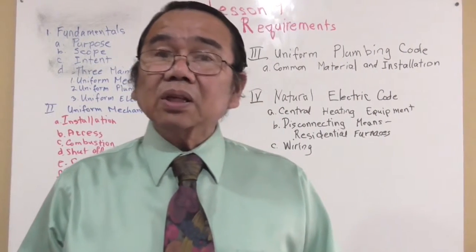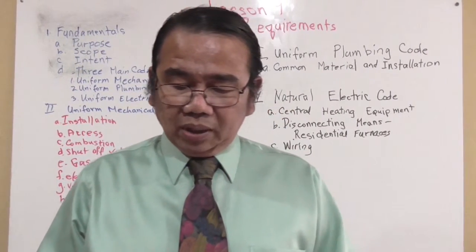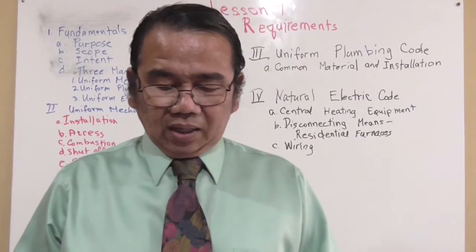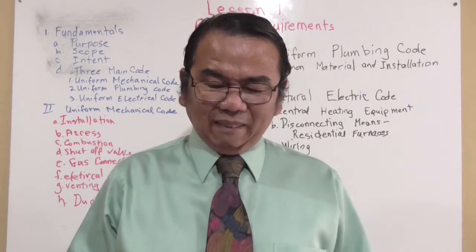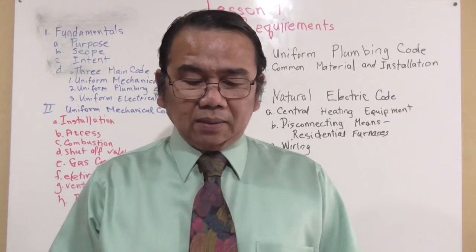Vibration isolation, if installed, shall be one between the equipment and the metal ducts, less than 10 inches in length. All ducts shall be supported equally. Okay, equally. That makes sure you support the duct.